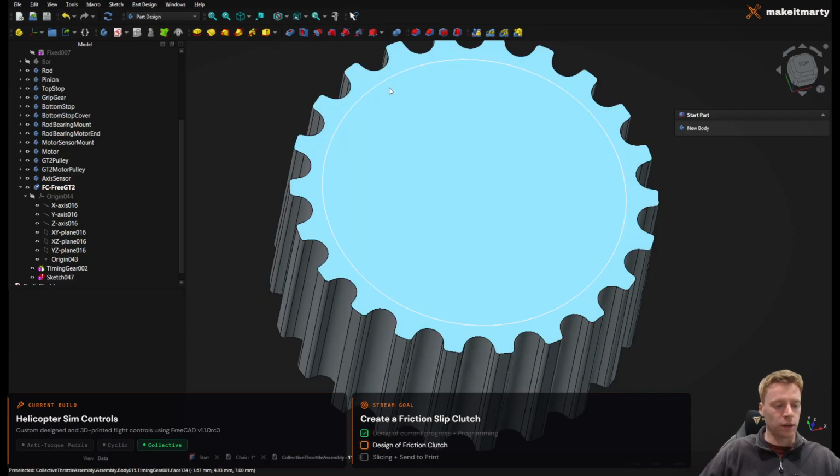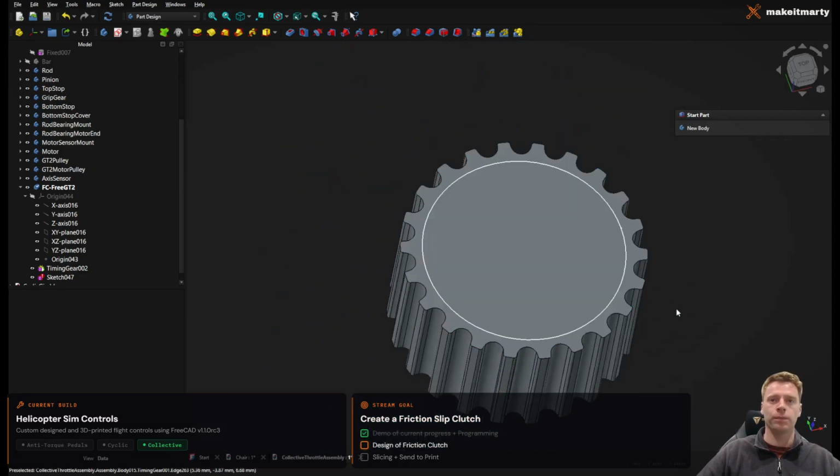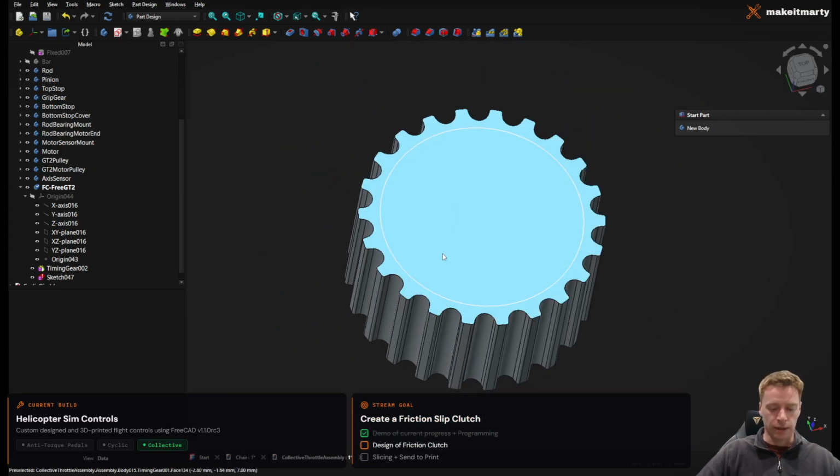And what we have, these small belts, one's 100mm long, the other is 98, I think, 96. So I can't make the gear too big, because then I'm going to fall in between belt sizes that I don't have. So let's give this a go. And then let's just check how big is a bearing. So how wide is the bearing? So the bearing is 5mm wide.